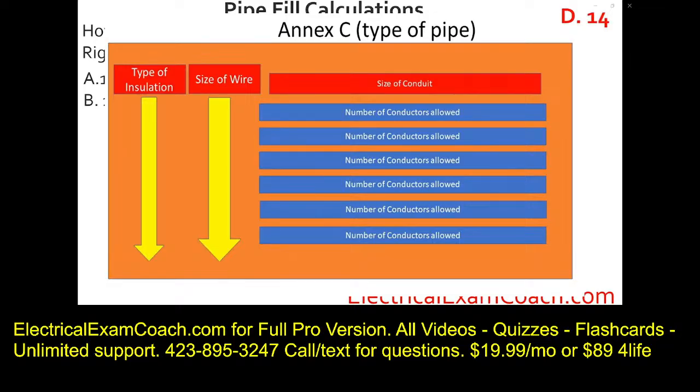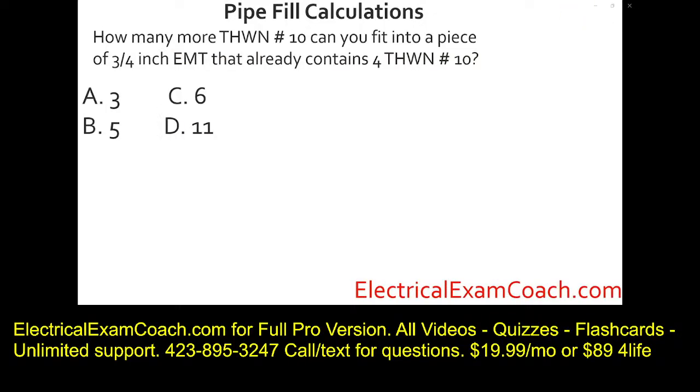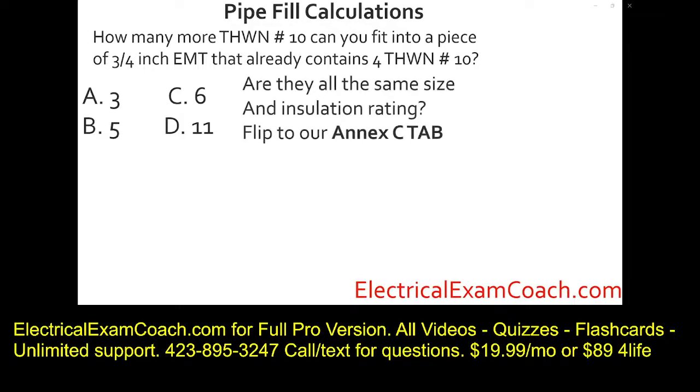Great job! How many more THWN number 10 can you fit into a piece of 3/4 inch EMT that already contains 4 THWN number 10s? The first thing we're going to ask ourselves, are they all of the same type and insulation? They sure are. So let's head to Annex C.